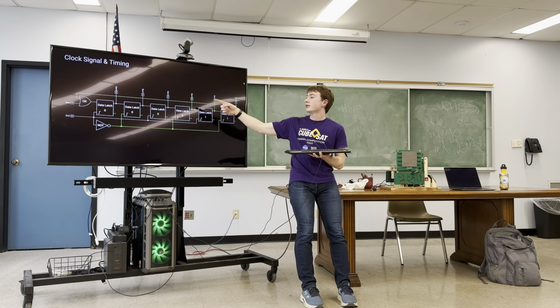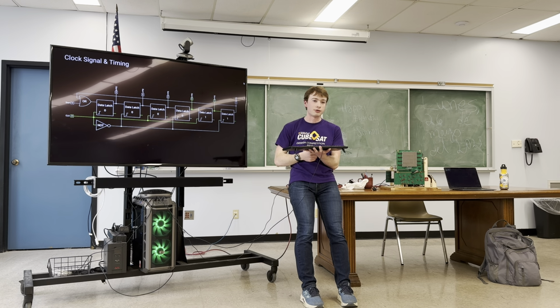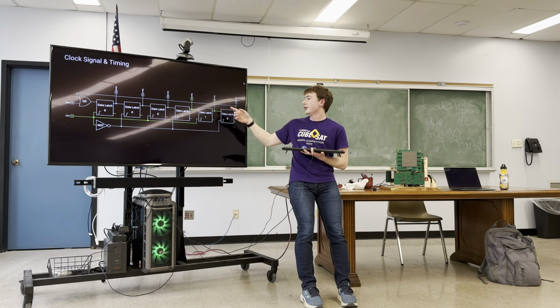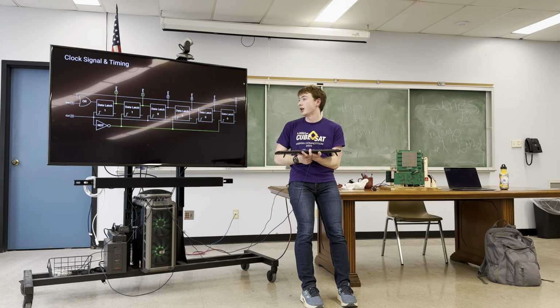So there are those outputs, and then it loops back. These can be chained together to produce more complicated signals to control things like reading and writing from memory and whatnot. This doesn't have to be so simple. This could go to some other sequencer somewhere else in the computer, based on what instruction is being run. It might be really complicated.